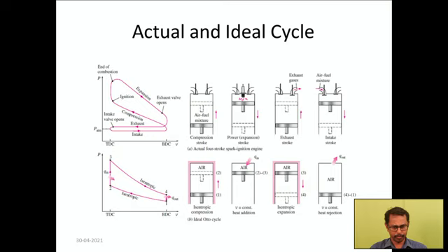During this expansion stroke, the power output is obtained from the piston and this power is transmitted through the connecting rod to the crankshaft, so that the useful power is available at the crankshaft. And in the exhaust stroke, the exhaust valve is opened. During this stroke, the burnt gases after power transmission exit to the atmosphere through the exhaust valve.